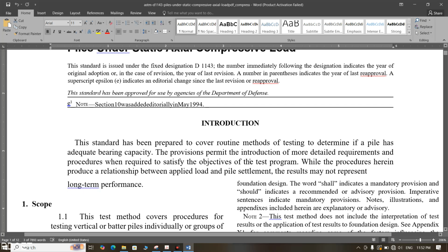This test is important to ensure that the construction foundations are free from defect and able to support design load. We have the pile test. Why is this pile test needed? This test is needed to assess the pile serviceability, design geotechnical strength, ultimate geotechnical strength or soil strength, testing to confirm adequacy of construction method, and confirm the pile shaft integrity.